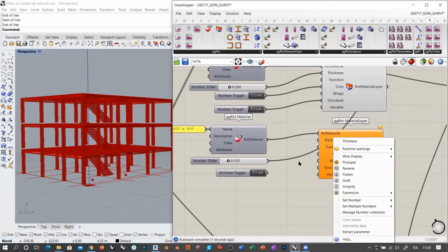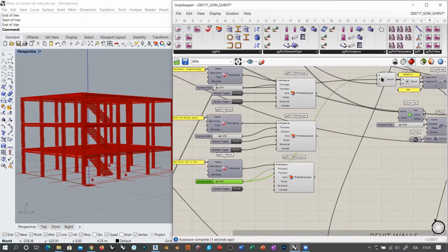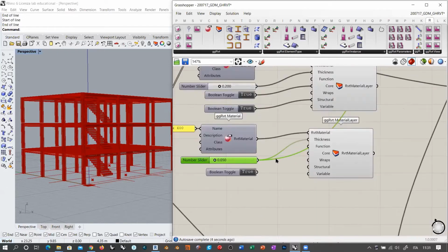The thickness is probably going to be something like, I don't know, here it depends on many things. You could also include some layer, for example, if you want some installations to pass through the ceiling and so on, eventually leave air in that case, but we are going to glue this ceiling to the structural element. So let's give this just 5 centimeters thickness. This is already affecting something here, as you can see, but we will discuss this in a while.